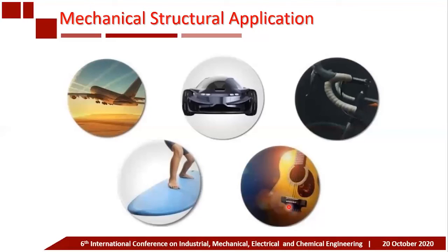These applications use complex epoxy formulations, which include multiple epoxy resins with modifiers for toughness, for example, or flexibility, or for flame suppression, fillers for strength, pigments for color, and curing additives that promote the curing reaction. High temperature applications can be improved by use of higher functionality resins, which increase cross-link densities and improve thermal and chemical resistance.